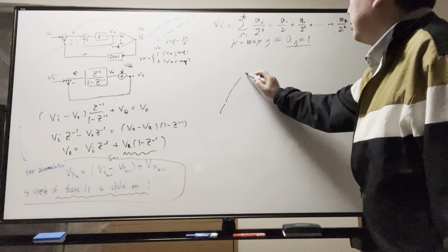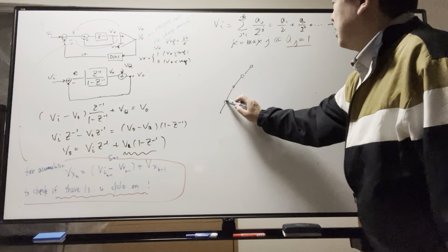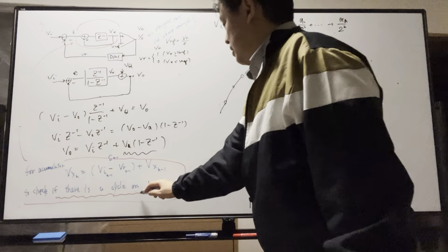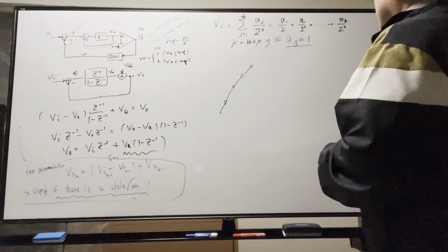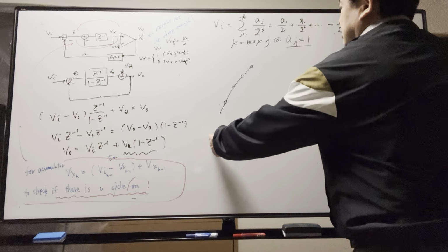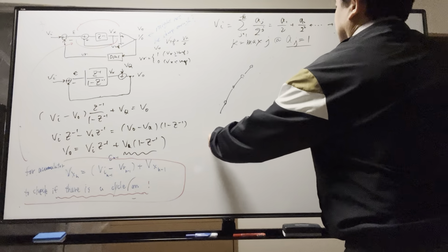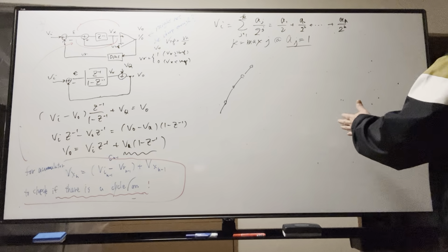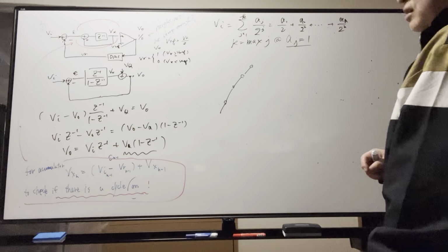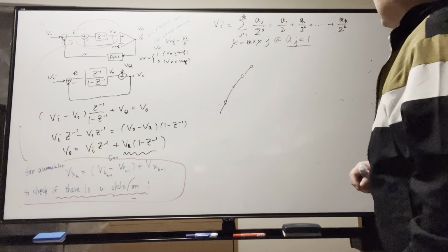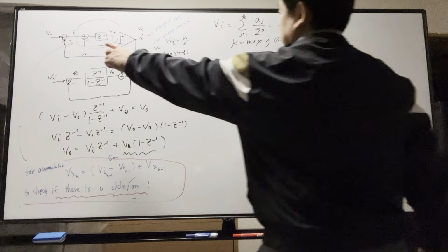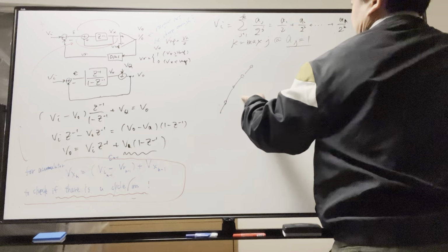Because a rational number has this kind of expression and has an exact cycle of m, if we select m samples and make m-bit words and apply appropriate filtering, like a moving average, we can recover the input after filtering.